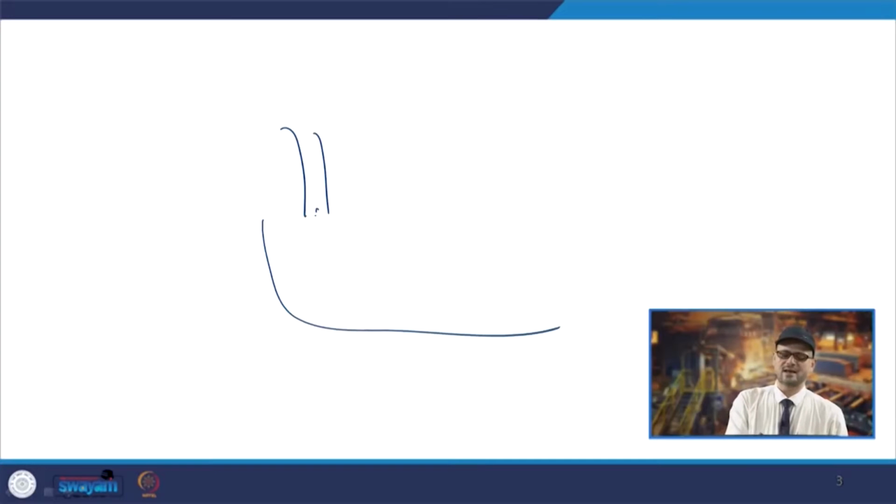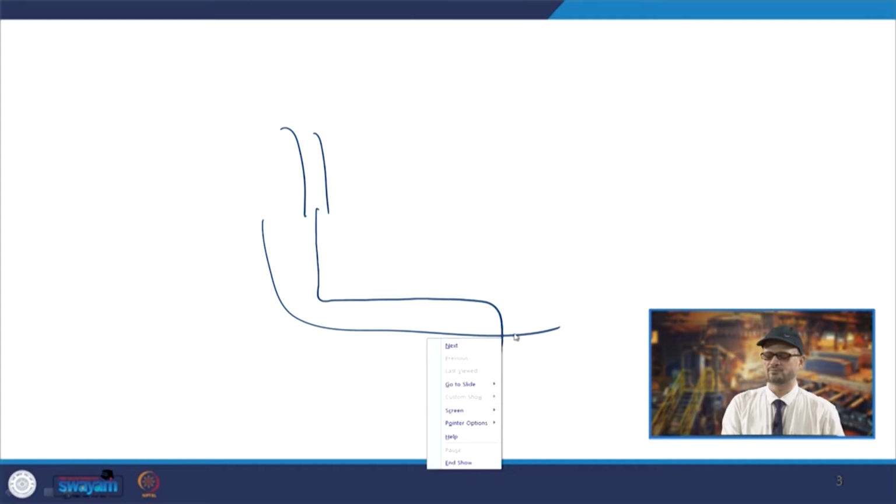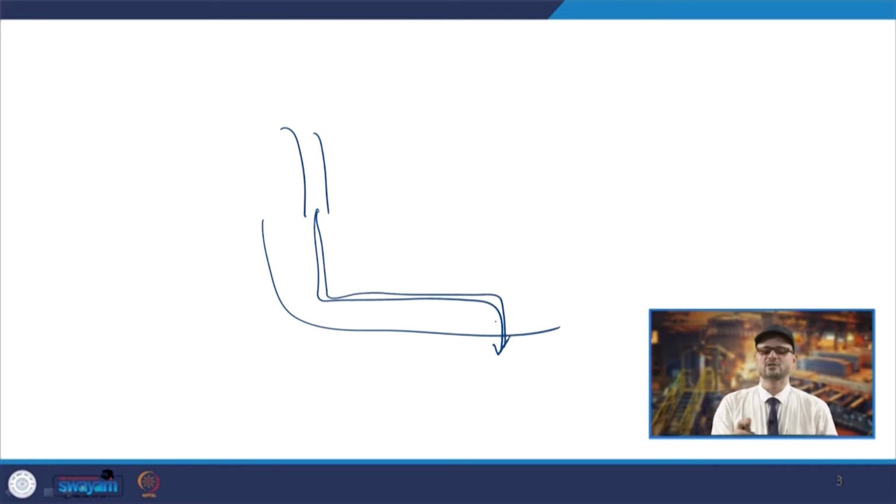This is known as the ideal plug flow. The tracer has entered the vessel, slowly gone through, and come out of the outlet. It has spent the ideal time. It has not interacted with other fluids, either in a longitudinal or transverse manner, and it comes out at the volume divided by the volumetric flow rate, that is, your theoretical mean residence time.